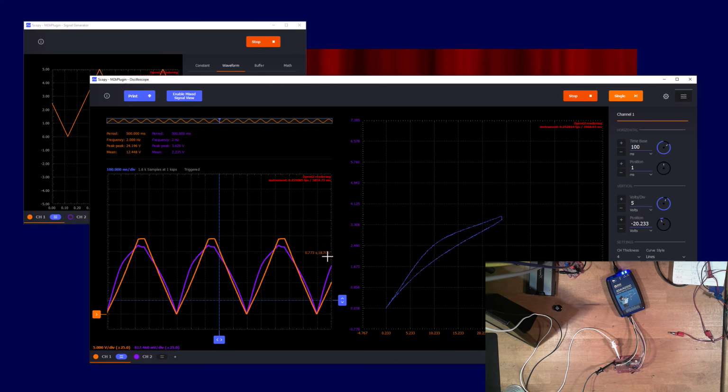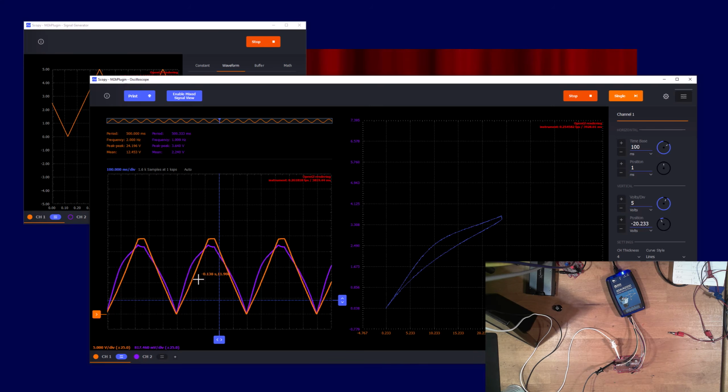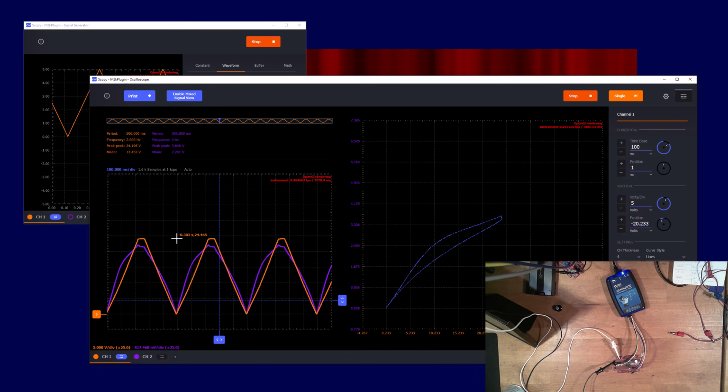And I'm not going to go through the math here. This is qualitative at the moment. Of course, whatever voltage I measure on that sense resistor, multiply by 10 to get the current, because it's a 10 ohm current sense resistor. You can see that my signal generator is railing out. That's the op amp hitting the stops here.